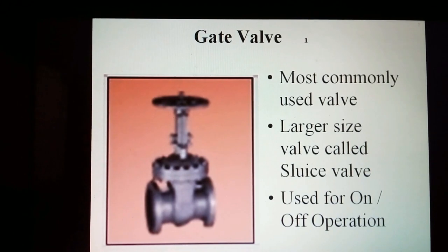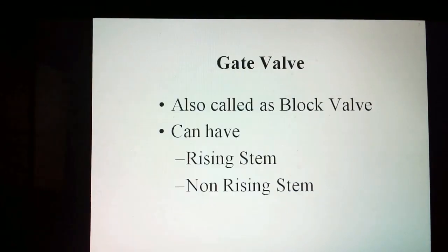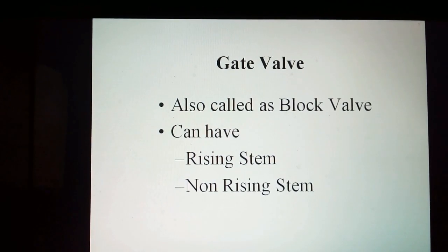Gate valve. There are different types of gate valves. This is the most commonly used valve. Larger size valve is called sluice valve. These are used for on-off type of operation. These are also called block valves. These can have a rising stem or non-rising stem.